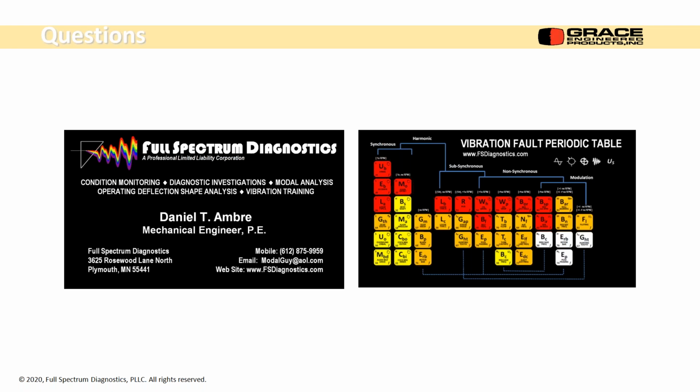You are resetting your statistical alarms with real data from the machine. And it doesn't lock you into every fan of this configuration having the same alarms. They're all different. Statistically it's close to that 0.325, but you're going to have enough data in a day or two to define a better statistical overall level that you're interested in as an alarm.